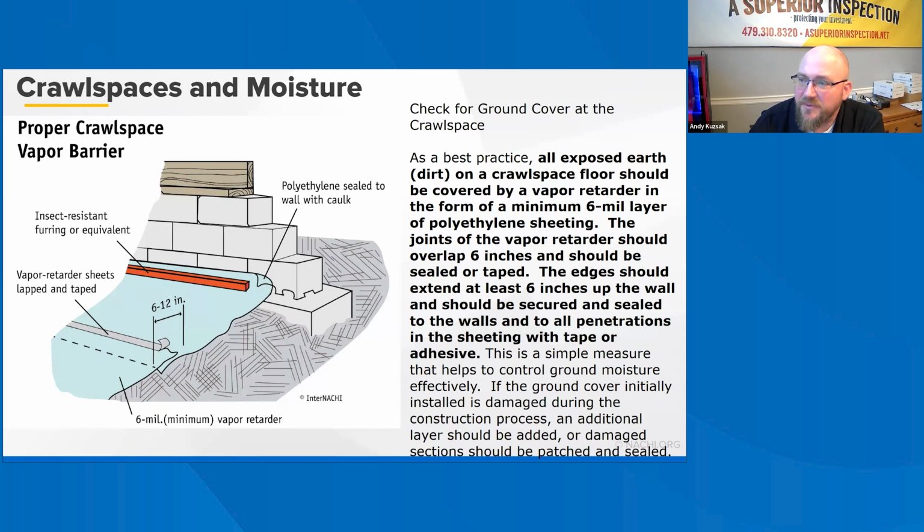Understanding vented versus unvented crawl spaces. Vented crawl spaces can minimize radon and moisture-related decay hazards by diluting crawl space air, but do not necessarily solve serious problems. Disadvantages include insulation needs against heat loss freezing, increased insulation area and cost, and potential moisture issues in wood. Operable vents can reduce winter heat losses and keep out moist air in the summer. Venting is unnecessary for moisture control if open to an adjacent basement and incompatible with crawl spaces used as heat distribution plenums. Unvented crawl spaces may reduce insulation needs and simplify installations, minimizing condensation hazards.